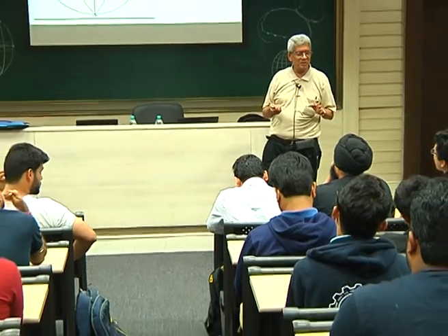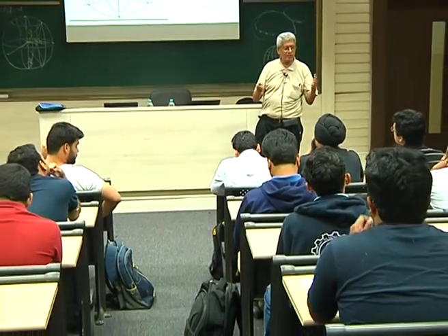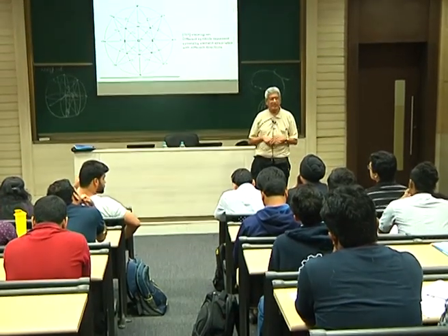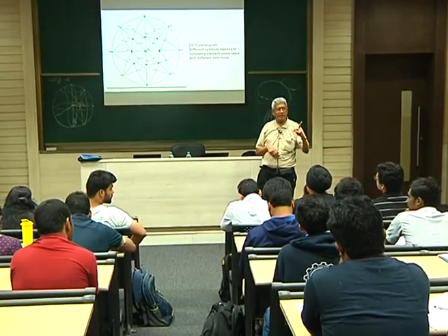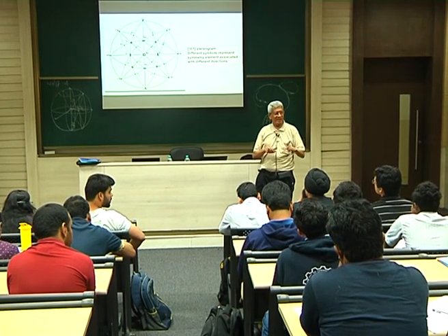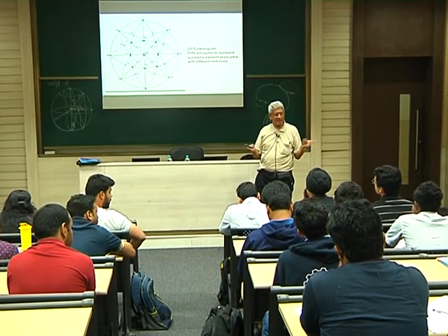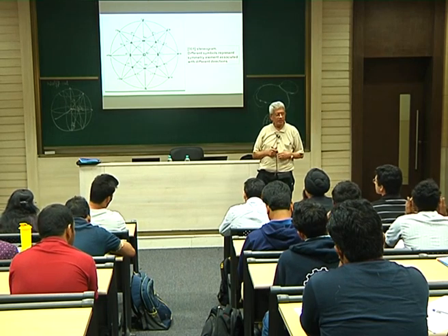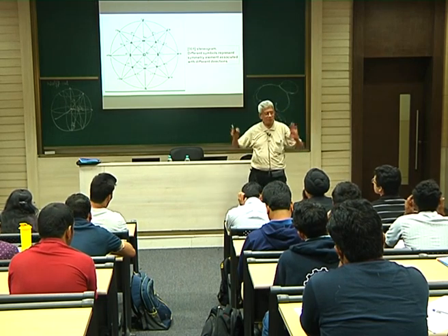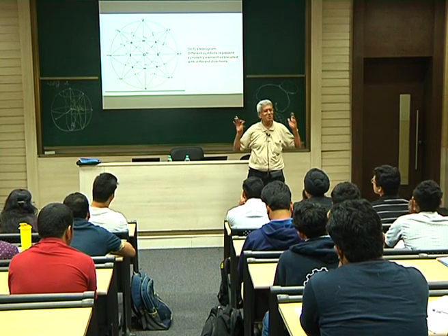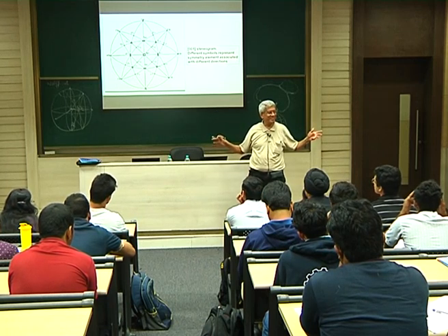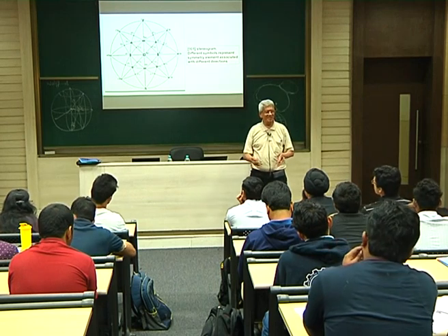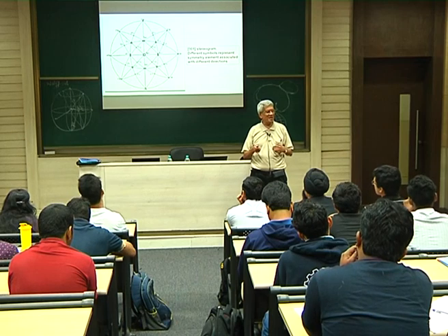Once you know the symmetry, like if I look at a triclinic system, if I wanted to plot a stereogram for a triclinic crystal structure where the angles alpha, beta, gamma are not 90 degrees and not equal to each other, and the a, b, c values are different, then the full stereogram has to be drawn, because there is no symmetry associated with it. Every point has to be calculated and done. When symmetry is there, that makes computational life easier.